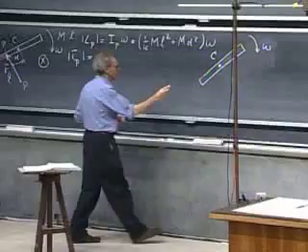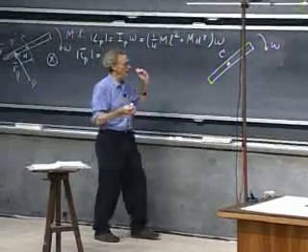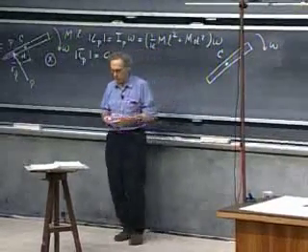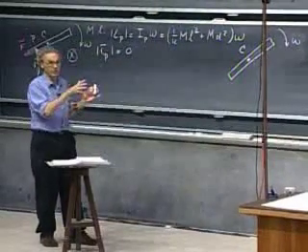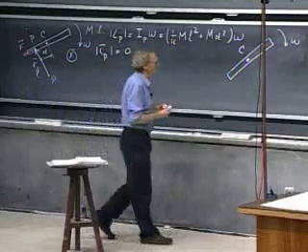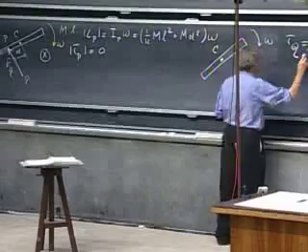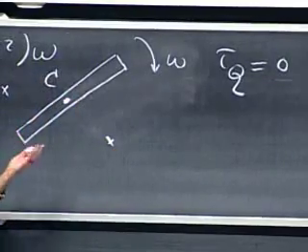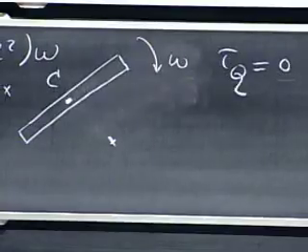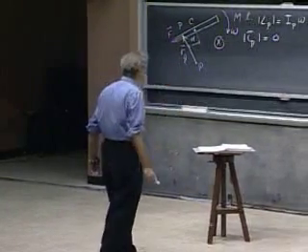Now there is no force on this pin because of the symmetry, which I just explained. So the pin is not pushing on the rod either. So there is no force at all if this is a frictionless object. So if there is no force at all, then the torque relative to any point must be 0. Not only relative to this point, but also relative to this point and relative to this point. Because if the force is 0, then any cross product of R and F is 0. So now you see the special case that I alerted to in equation number 6.